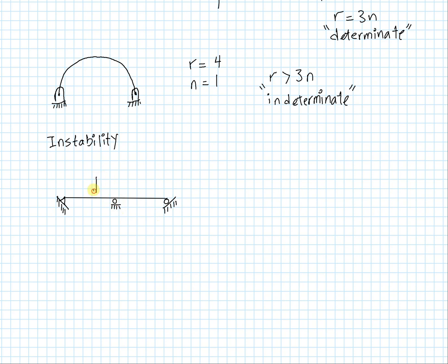If I were to apply some physical load with a value of P, I would have reactions, which I'm going to draw in different colors, that would look like that, and perhaps like that. And so if I retraced all these reactions back to some central point and looked at where they coincided, and if they all sort of coincide at a single point, then that becomes problematic, because basically I can have instability issues.